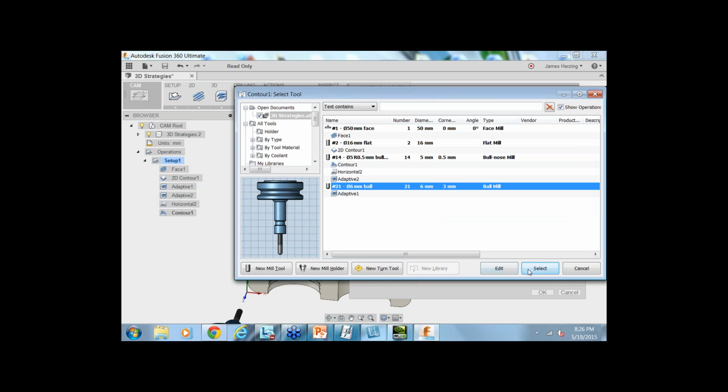Just a quick thing on that last point before you get going. If you did one quick operation in there where you just set it, but didn't state why. You stated that you were going to go slightly below the surface, to a negative surface. If you fail to do that negative value, it will also machine the top surface, because it's selected as a flat surface.